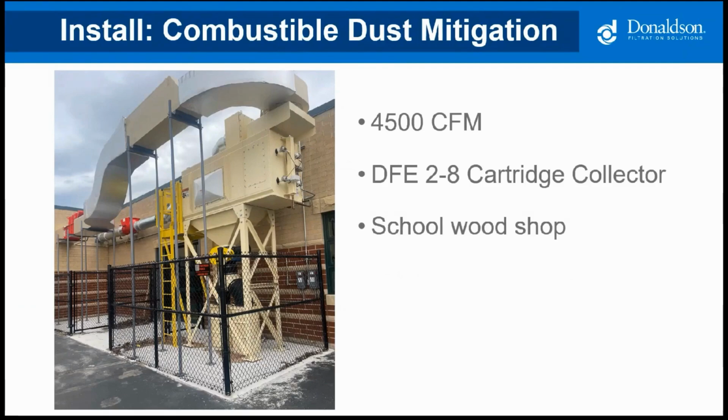The dust was combustible, and as part of the mitigation strategy, they went with inlet isolation, a high-speed abort gate, an explosion vent, and dust discharge isolation. In the photo, you can see our small DFE collector with the explosion vent on the side where the white rectangle is. You may notice underneath the hopper, we have an NFPA-approved rotary valve, and in the left of the picture in the duct runs, you can see the inlet isolation valve as well as the high-speed abort gate.